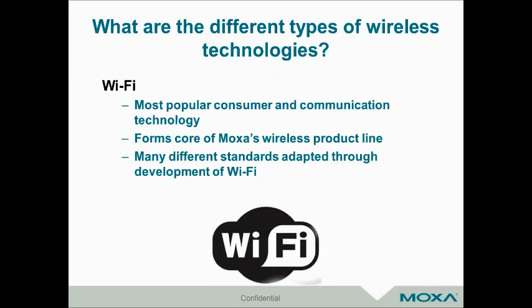The really nice thing about Zigbee is that the radios tend to be very low power. So if you've ever used any wireless technologies before, you're probably aware that most of them have a fairly decent power draw. And Zigbee is kind of on the very low end of that spectrum. So it's great for battery-operated devices or things that are remote and don't need a large dedicated power supply.